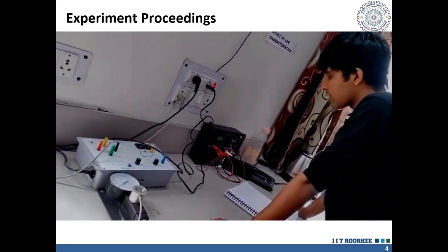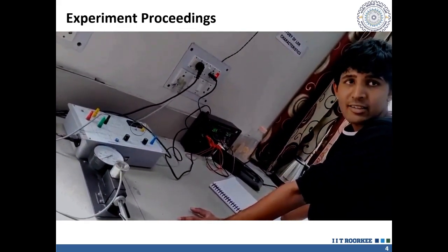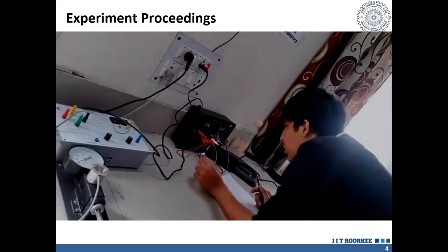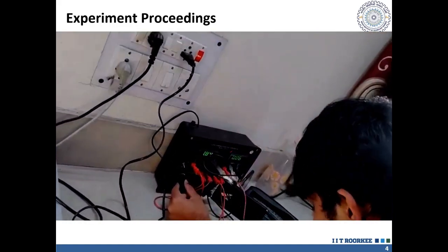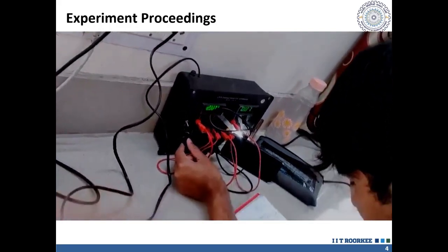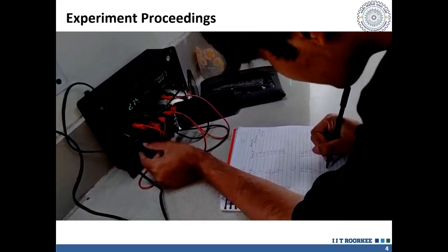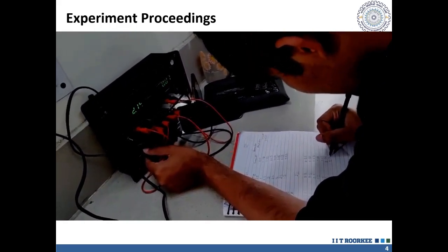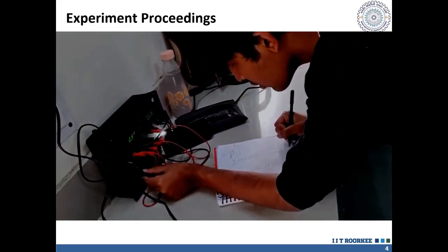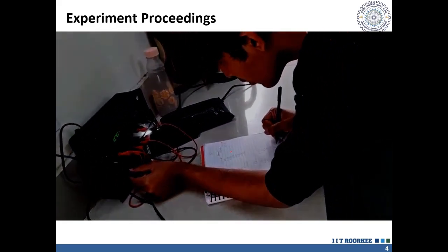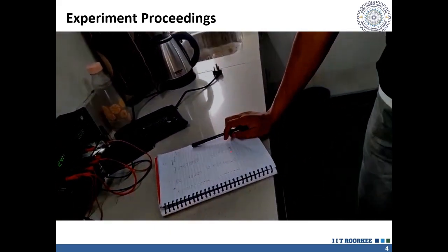This shows the linear response of the LDR, and the output provided by the LDR is linear and almost intercepting at 0. We can consider the output of the LDR to be ohmic. Then we'll also see how the intensity of the LDR is related to the resistance. We have taken 8 readings till 2.4 volts and we observe linear behavior in these cases.